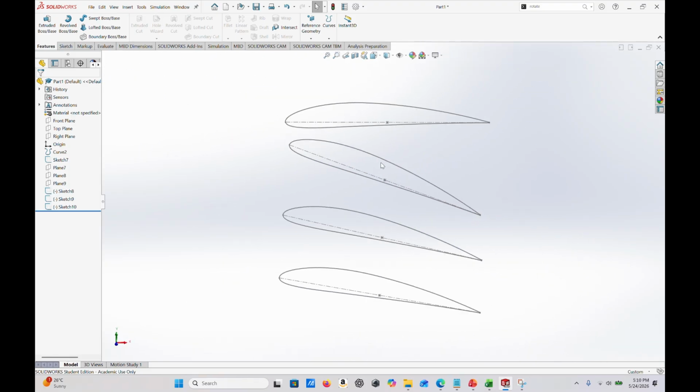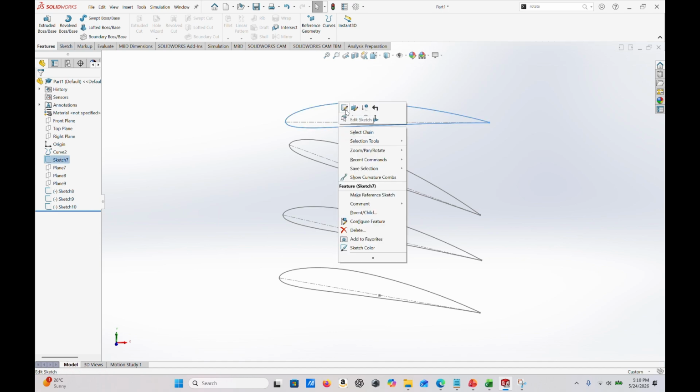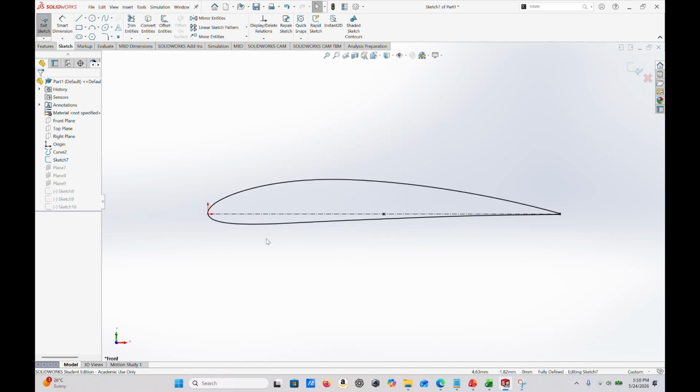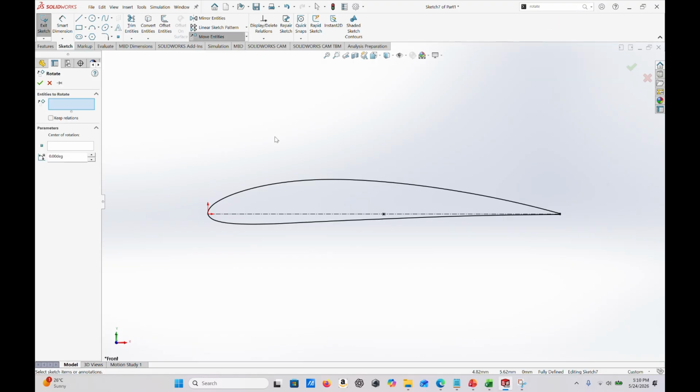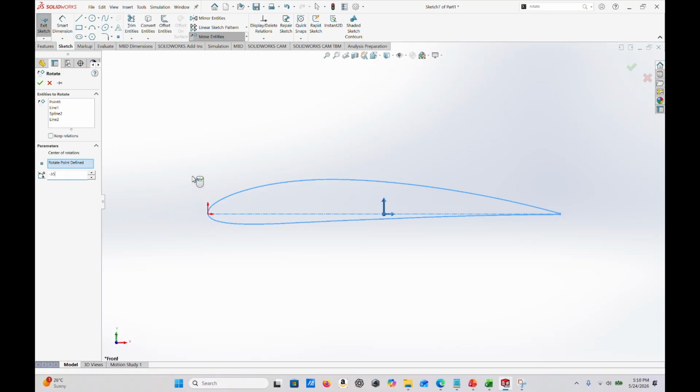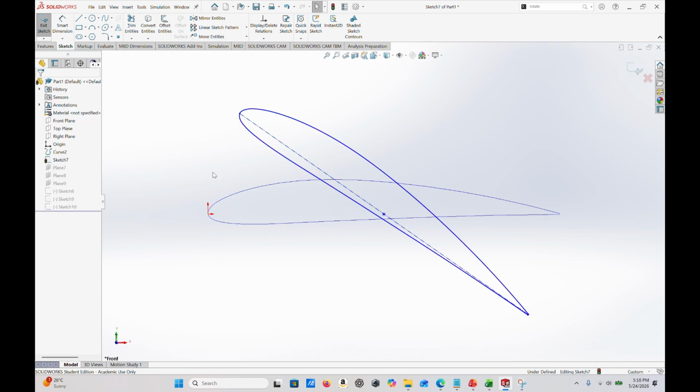Now we're finally going to edit the final sketch. Do the same process again, where we go to rotate entities and highlight. Here it shows the highlight, which is a bit weird. Maybe it only shows it for the ones on the origin of the sketch, and maybe it doesn't do it for the converted entities. But in any case, this is basically what we have done. And we got negative 35, and the curve is still there, as you can see.